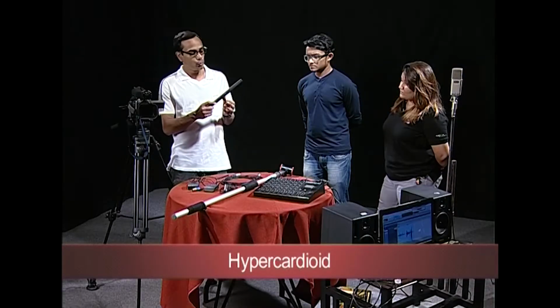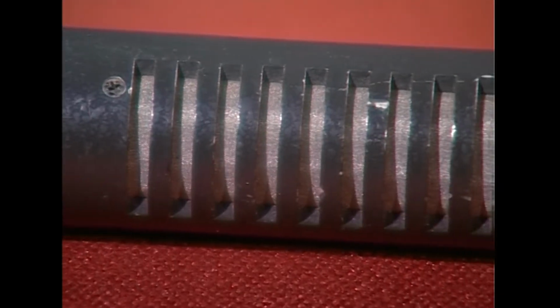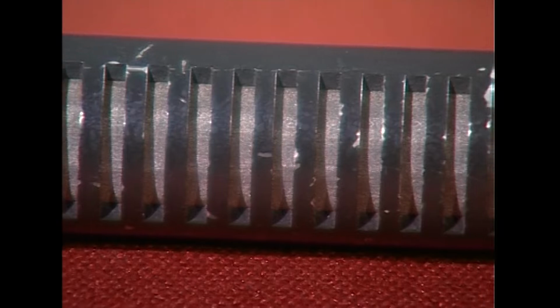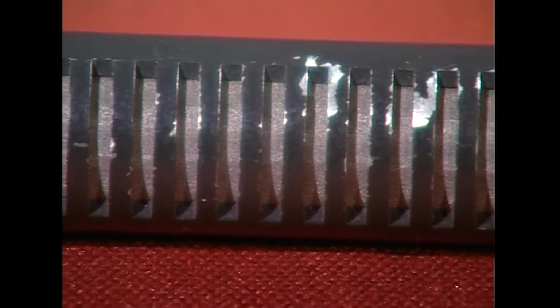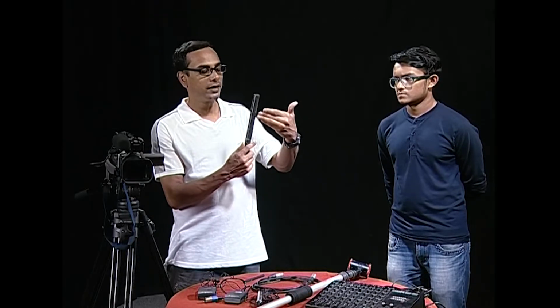Now, this microphone has a standard cardioid capsule inside, but at the same time it has been made hypercardioid just by using this nozzle. You will see this nozzle has certain slits cut on the sides. These slits are designed so as to avoid any external noise coming into the microphone from the side. Whichever sound goes into the microphone through the sides will be converted into off-axis noise by the other slits, and will be cancelling each other out.